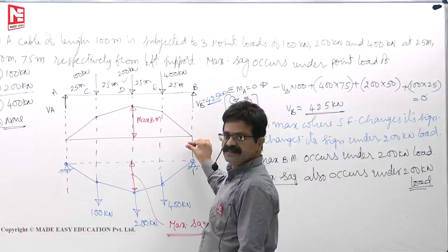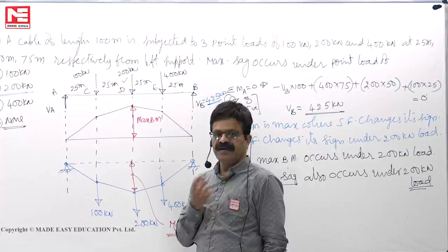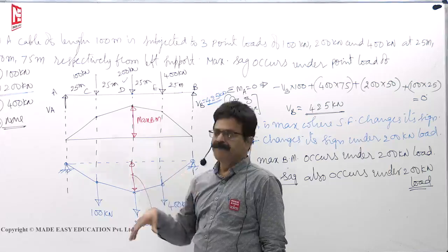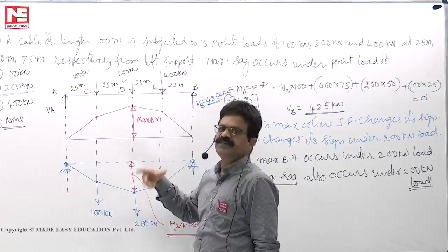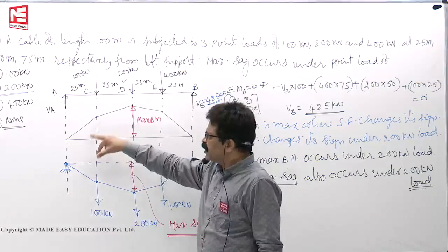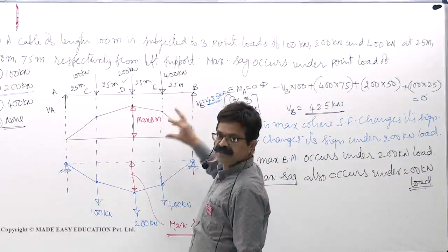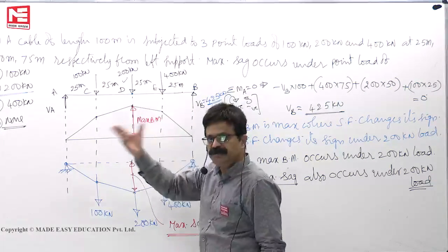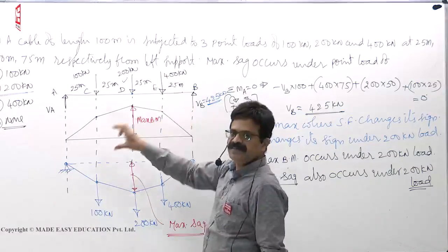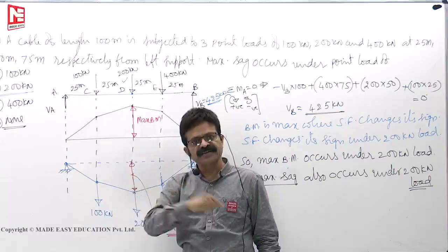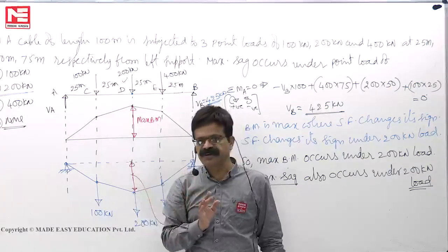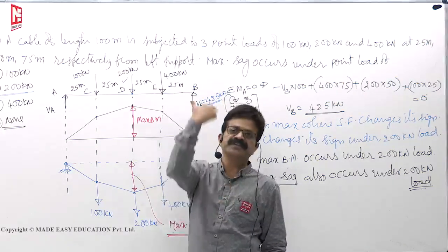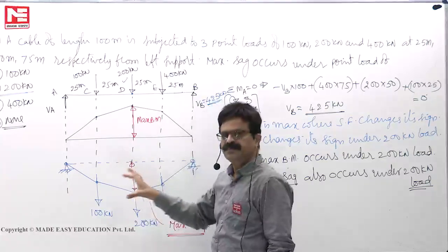So, if you build a structure in this shape, that is called a theoretical arch or linear arch. In a linear arch, if you build it, bending moment is 0 everywhere. So, that is first told by Professor Eddy, so it is named after him. But if you are not able to build like this, if there is some error in building like that, then the bending moment in the structure will be directly proportional to the difference in the ordinates, the difference in the error. From the theoretical arch, your actual arch deviates, let us say, because you could not build correctly. The more the deviation from the theoretical arch, the more is the bending moment in the actual arch. Like that. That's what Professor Eddy says.